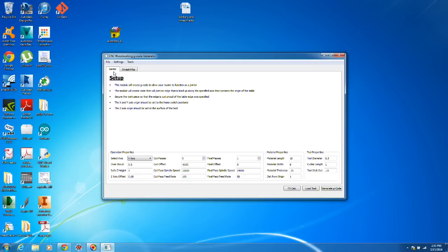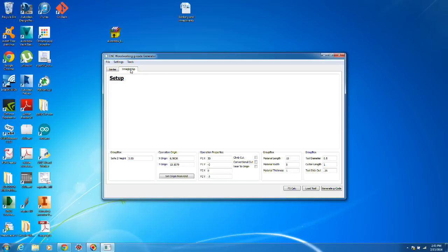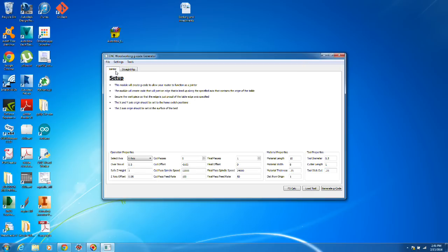So right now, the one that I have working completely is the jointer. I'm very close to getting the straight line rip working, and other operations that I want to do are profiling, and I want to do basically every kind of dovetail that you would want to do or could do with a dovetail jig, including the Incra style dovetailing. That will take a little bit of time because it's a little bit more involved, but I thought I would just get my feet wet doing this, and it actually works and produces usable G-code that functions as you'd expect.